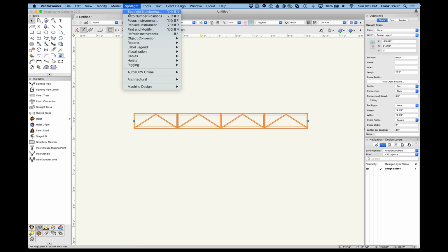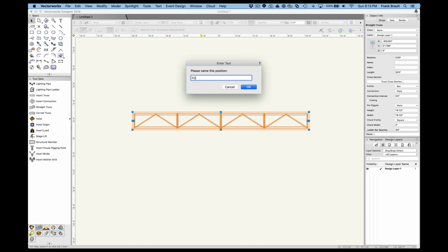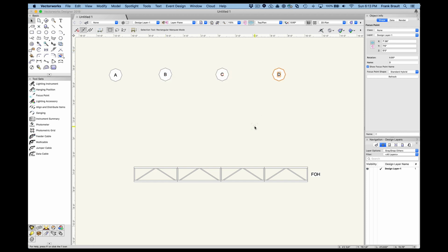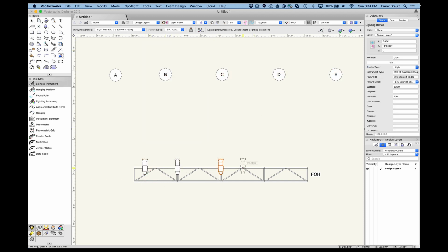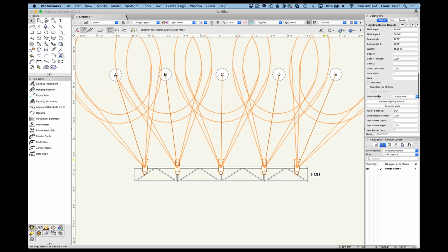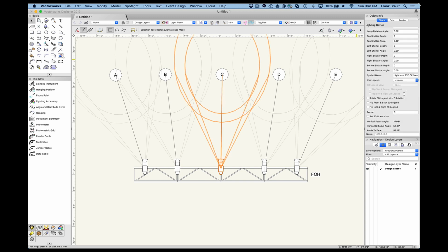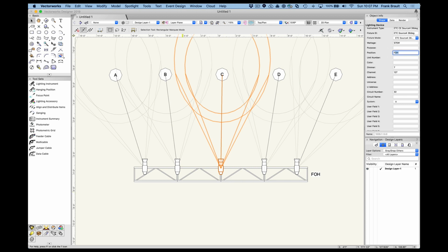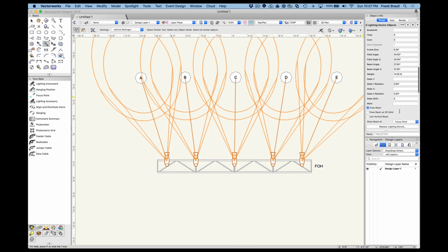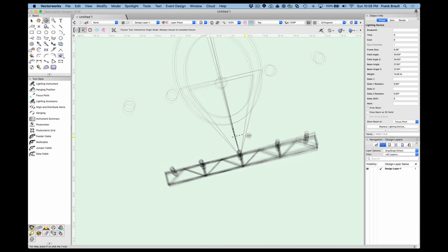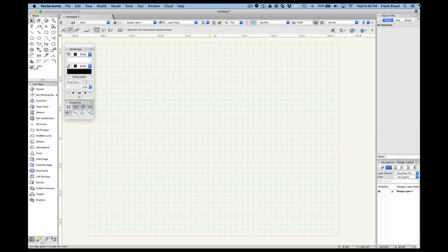From an organizational perspective, this may seem quite different than pencil drafting with lines and a scale rule, or from other CAD workflows that you may be familiar with. But the benefits far outweigh the conceptual leap you are making as you eschew the 2D workflow in favor of a model-based workflow. For example, making changes late in the design process with a model-based workflow is significantly easier and more reliable, because instead of trying to adjust all the views that are affected by the change, you are instead directly applying the change to the model once, and then simply asking Vectorworks to recalculate all of the presentation views where that change affects the documentation.